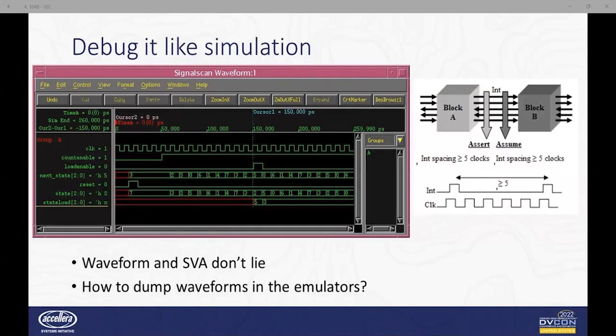There are two types of emulation platforms, the FPGA based and the custom processor based, namely Protium and Palladium. Protium runs 10 times faster and costs less than half of the price, but it takes 2 days to recompile a build to add some signals to the waveform, and there's a limit on the number of signals it can probe. On the other hand, Palladium has no such limitations.